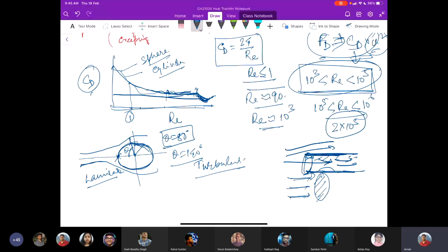So you are disturbing the laminar development or the laminar flow by introducing the surface roughness of these blunt bodies, and you are onsetting or triggering the turbulent boundary layer condition quickly. And for that, we have seen that there is a decrease in the drag coefficient.